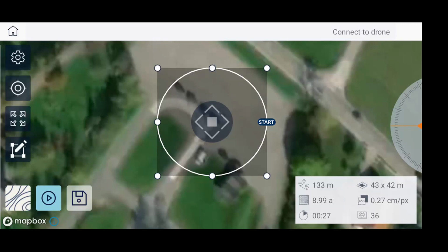So we advise you to start with the higher circle at 20 meters, then go to 50 meters, and then even lower to 10 meters. And this is the best approach to get an accurate 3D model. So this is everything about the planning in the 3D Survey Pilot app. Let's go now to the office and see the results from the field.